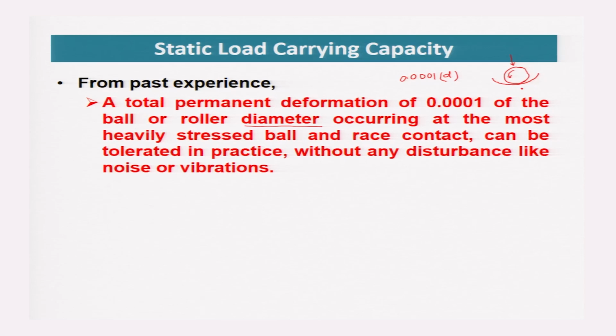So without crossing the limit of permissible noise and vibration, 0.0001 times the diameter of either ball or roller deformation is allowable.